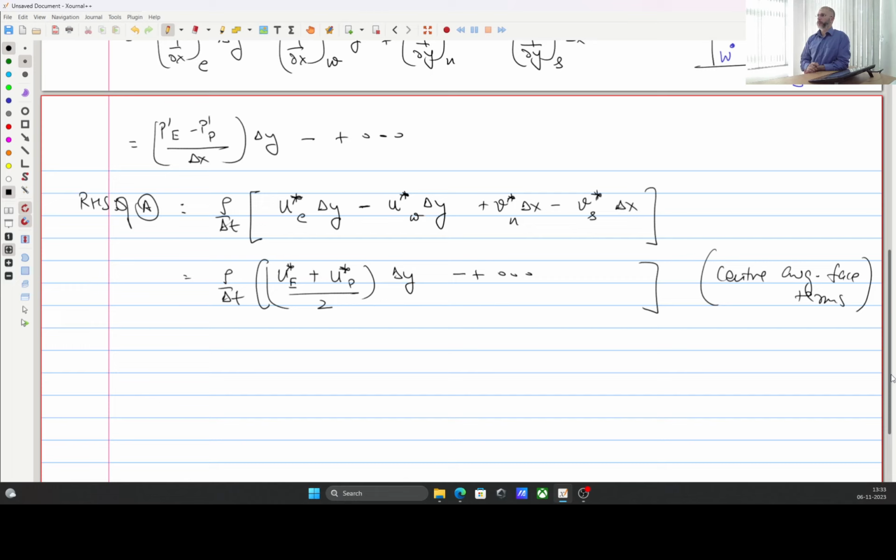So you have to solve that equation. We can use a Gauss-Seidel method to solve it with the ideas of over-relaxation, successive over-relaxation, and so on. So those ideas, you know how to solve these linear equations iteratively. Or what you can do is you can also use pseudo time stepping. So you can add a del p prime by del t term, and then you can use an explicit approach to solve it by time stepping till steady state, whichever approach you would prefer.